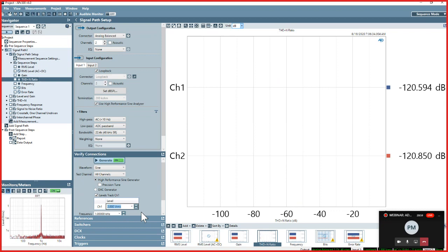And this defines a bit of the lower bound for a device that we could measure. That is to say, if we were measuring a device that had itself a THD+N less than minus 120 dB, it would be difficult to measure it because we would be unable to separate the residual noise and distortion of the analyzer from the residual noise and distortion of the device under test.